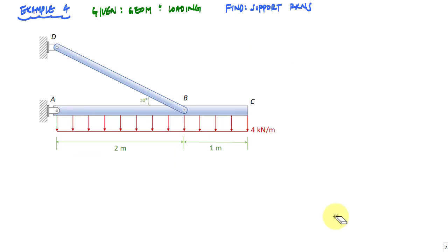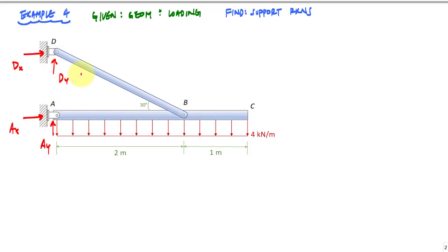So I've got here this beam ABC. It's pin supported at A, and then it has this rod BD connected to it, holding it up. A lot of times students will take this diagram, see the two pin supports at A and D, and they'll end up drawing this. What we'll have here is 4 support reactions, and it will seem like it's unsolvable.